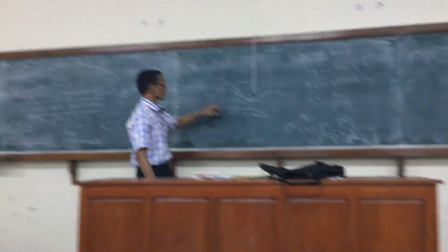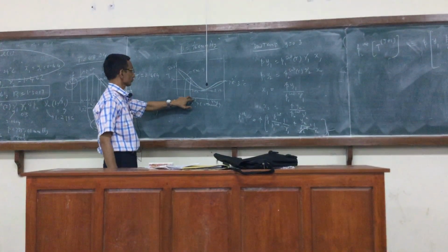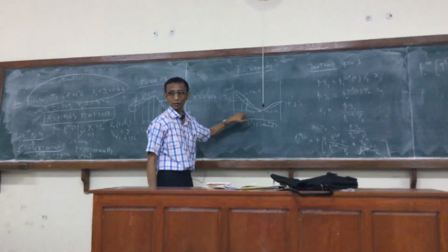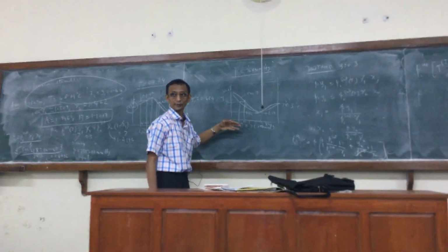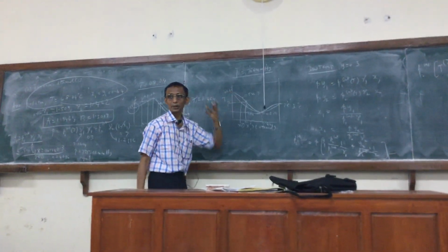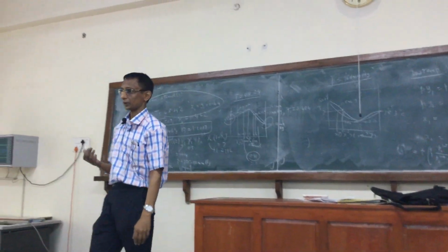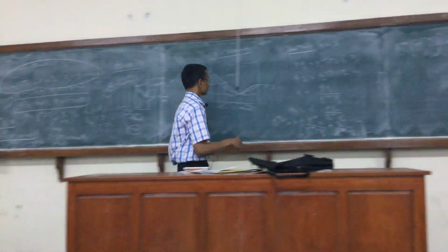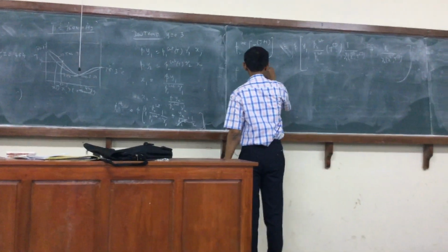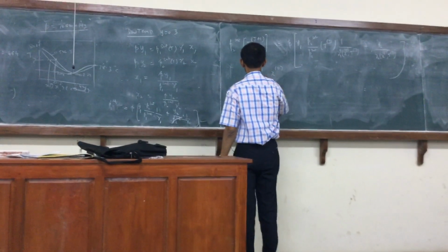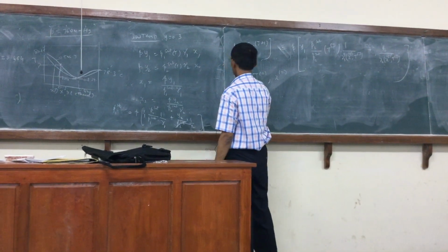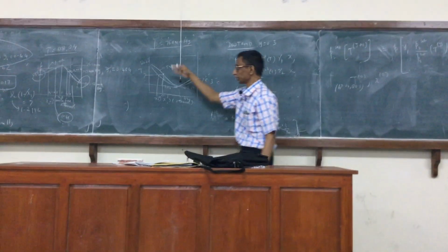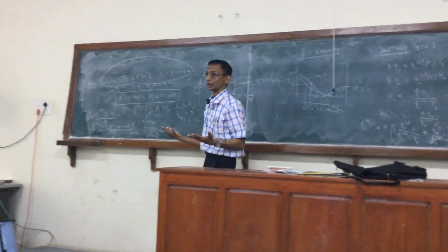Right? So you can say roughly, if it's 0.3 and this is 0, so between 0 and roughly 0.45. Right? So I want a value at 0.3. Roughly 2/3 of the difference between this can be an assumption. Then we are assuming a certain linear behavior. So I can assume a T naught. T naught will lie between 68.24 and 80.1. But you can approximately assume it's linear and choose the temperature, or just choose any temperature between the two.